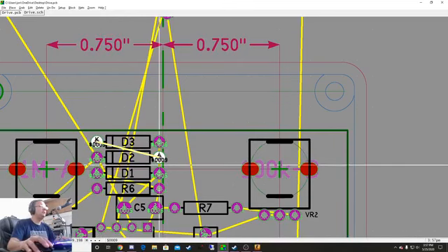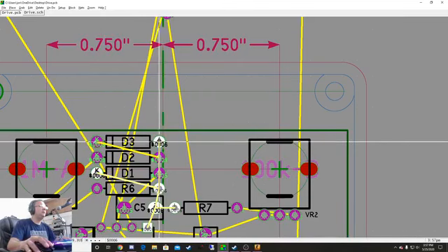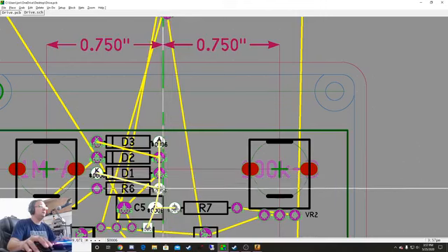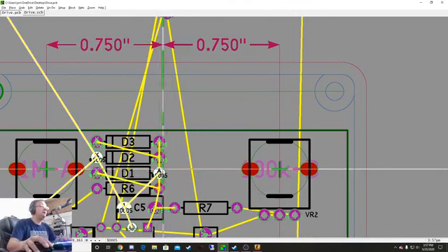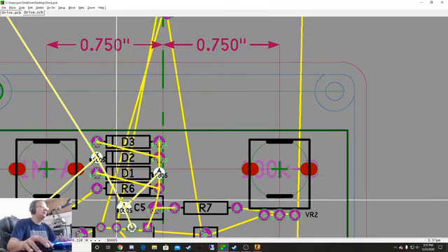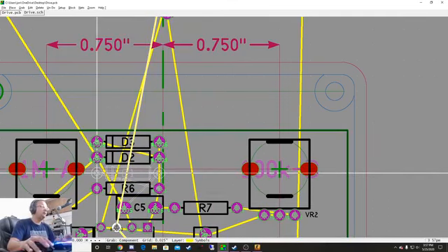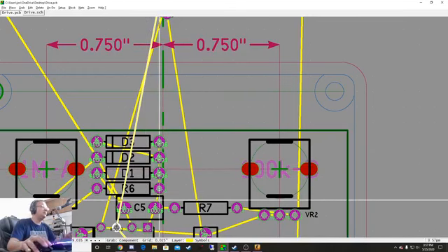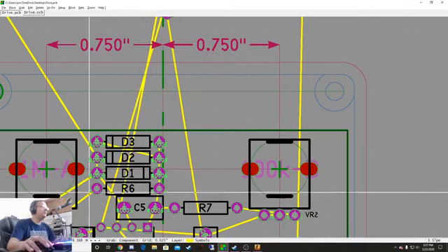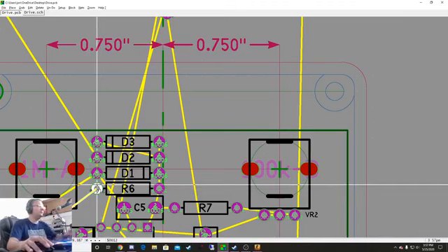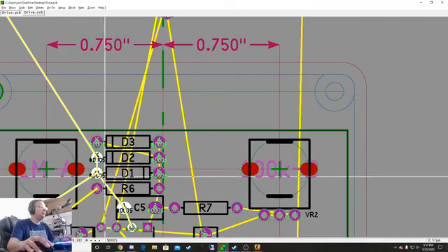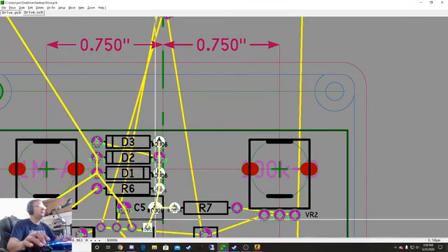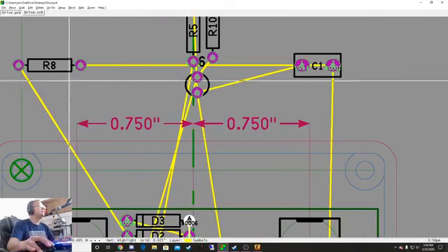I have one trace that goes there. I would have one trace that goes here, around here, and then it has to go up over there. And this trace has to then cross it. And so the reason I did it this other way is so that those traces don't have to cross. So we'll move forward with this for now. This resistor is going over to the pot. The other half of that pot goes back over to here, leads back to that. So we've got that routed.